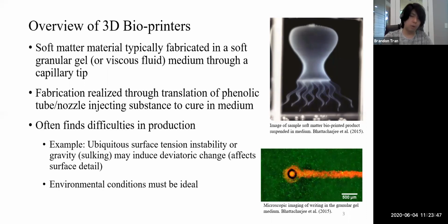There are often difficulties to define. One is that if you're 3D printing a subject and you're dragging the material onto whatever plate or medium you're putting it in, dragging the material causes shear tension on the surface. So you deform your material and cause a little peak spike.